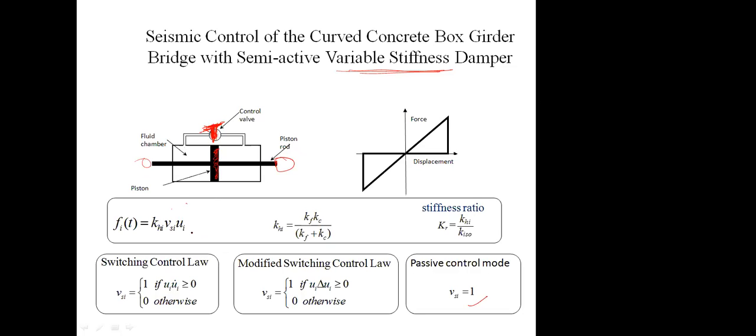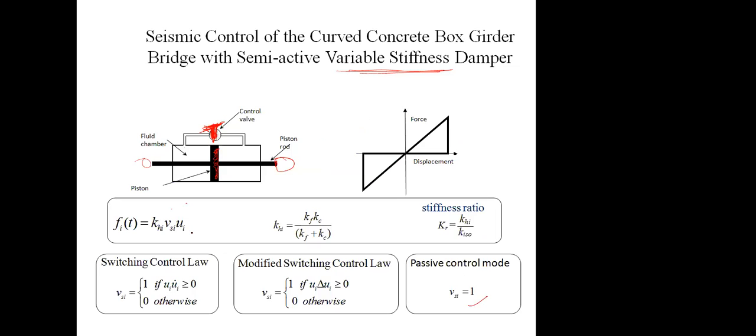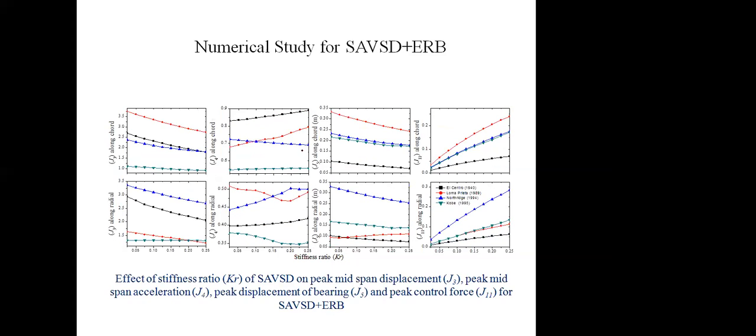This is a very simple one in which it mainly depends on the stiffness ratio. Whatever stiffness we are going to provide here, as per the fluid viscosity, we have to consider only for the analysis for optimization purposes. I did this for my bridge structure. It was observed that a lower value of the stiffness ratio is beneficial in the case of all LRB and APS.